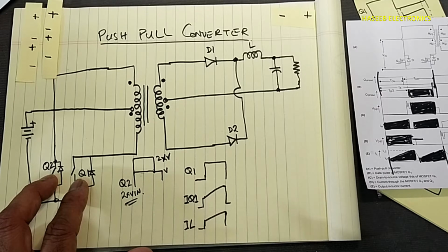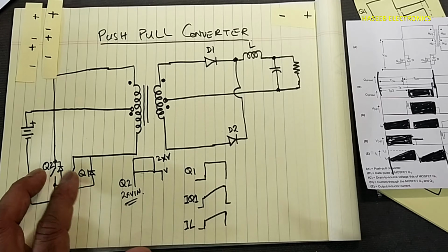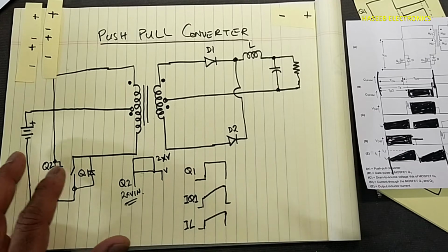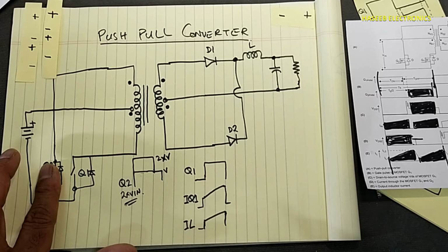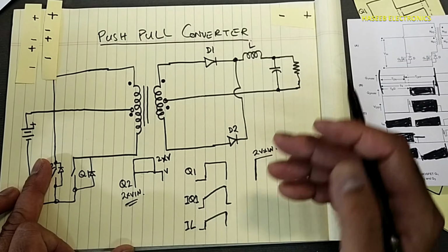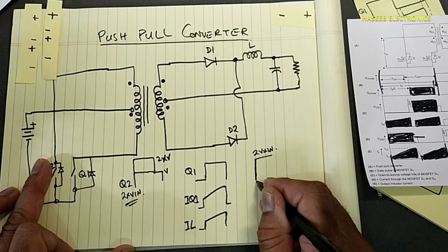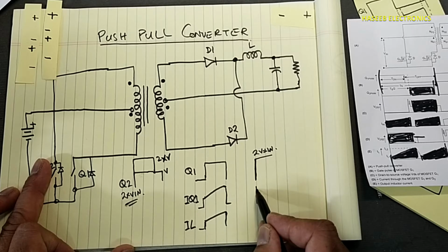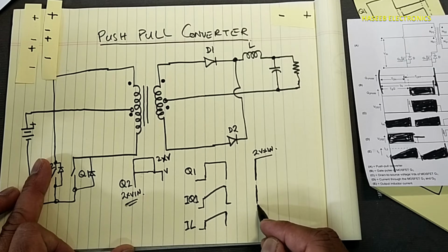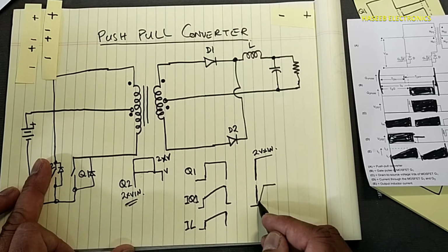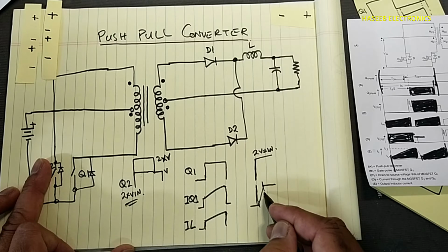This is the drawback of this topology, that the switching device always receives more than two times the voltage as voltage stress. When any switching device has high voltage on its channel, when it turns on or turns off, it will not turn on immediately. It will take a turn-on time to go from 10% to 90%.